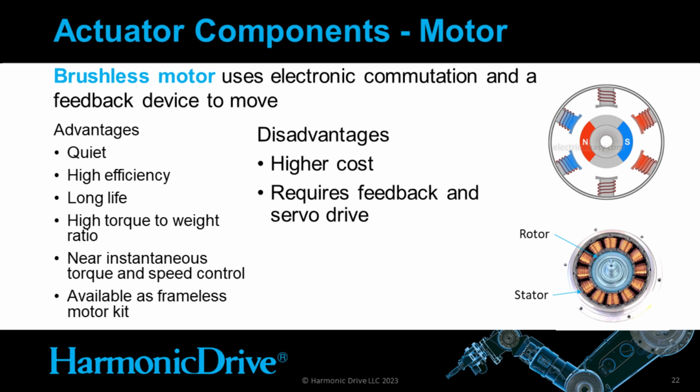In the bottom right side, I have a picture of a frameless motor installed into a housing, and on the inside, the rotor is coupled to a custom motor shaft. Some of the disadvantages of a brushless motor include their higher cost and that they require feedback and a servo drive.